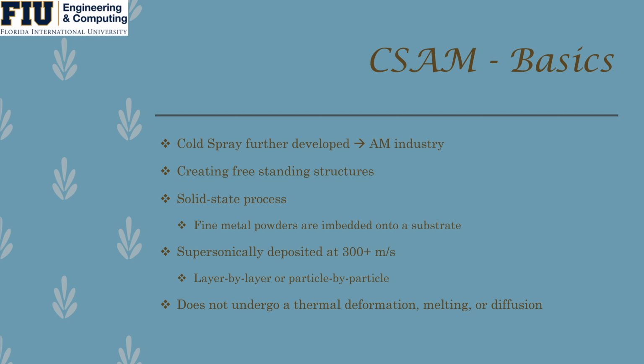Some of the basics of CSAM. This is pretty much cold spray further developed by the additive manufacturing industry in order to create freestanding structures. As with cold spray, this is a solid state process in which fine metallic powders are embedded onto a substrate. They are embedded supersonically at greater than 300 meters per second.